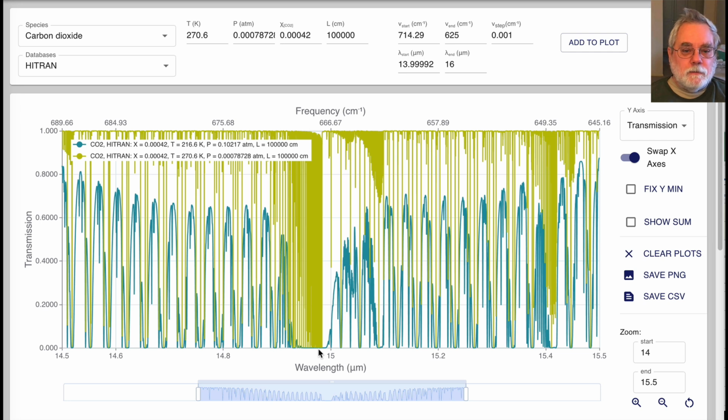This is why I reduced the step size. Had I not reduced the step size, the plot would have been wrong and I might not have known it. However, when we reduce the step size, we typically have to also reduce the wavelength range because the tool only allows a fixed amount of calculating time per plot.